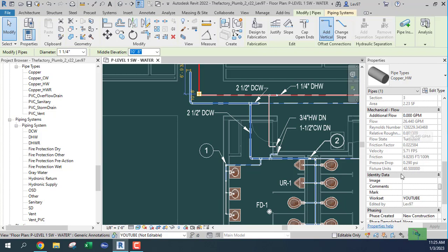If I go to my table at 40 fixture units, I get 25 GPM for flush tanks. So it's starting to diverge as I get less and less fixture units. So at 40, it starts to diverge a little bit from the curve, or it starts to converge to the curve, because we know at 60 fixture units, it's at 32 in this case.